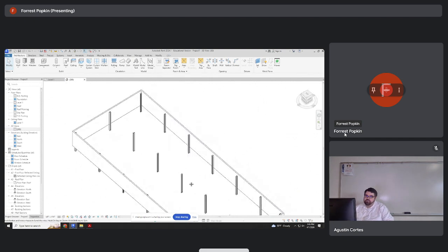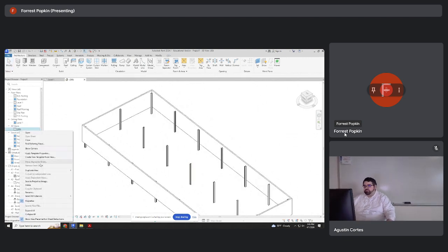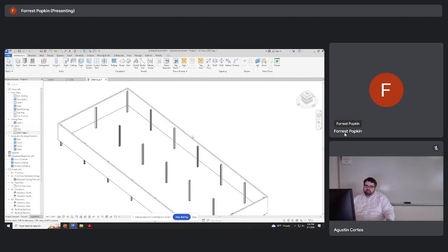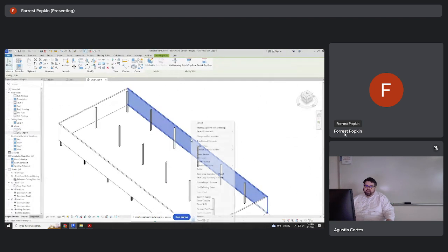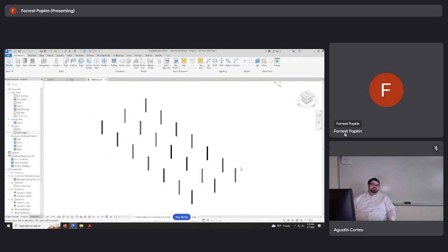So when you do a 3D view, of course, as you probably know by now, I can go to duplicate view. I can duplicate with detailing. And if I have other things like walls and stuff that I want to hide, I'm able to just go to hide and view by category. And if I do that with enough stuff, eventually I'm just left with my superstructure, right?